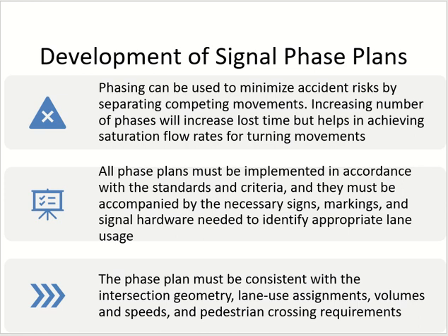Okay, other thing, look at the local standards. Consider the local standards. Okay, so here we have right turning, right? So right turning is allowed. You come to the signal, you have the chance, you will take the right turn. Okay, in Pakistan we have the left turn, because we have left hand drive. Okay, so these are the local standards. So the phasing plan which is working here will not work in Pakistan.